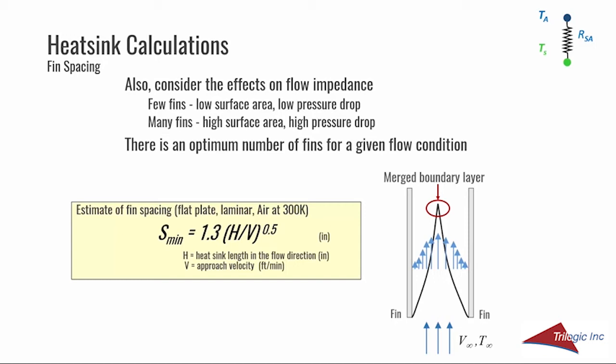As the flow is developing, the fin will have the maximum heat transfer rate per unit length, but also the highest pressure drop per unit length. When the flow is fully developed, these values remain constant.